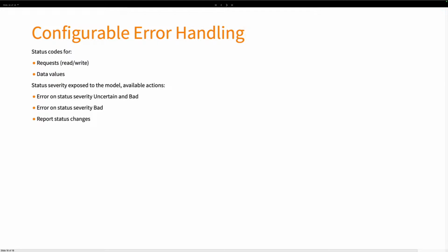So selecting any of the last 2 options means that we could do error handling in the model. Maybe the bad value isn't that important to our operation, or we can shift to a different operating mode to remedy the situation. To aid in the decision making, the components also come with timestamp outputs, so that it's possible to take different action depending on how long the value has had the current status code.